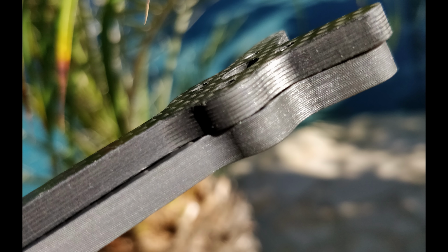It's super hard to get, close to impossible. Yeah, I would say in reality, impossible to get the resin into a laminate that is that thick. Aha. You cannot get the flow to work. So it has to be in there to start with, especially if you're doing this under pressure.